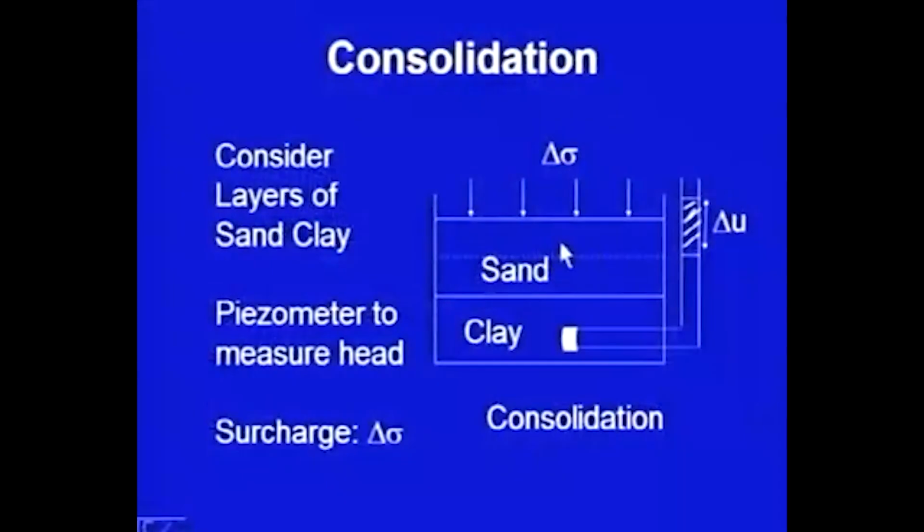Let me try to explain it technically. Here is a site, which has a sandy layer underlain by a clay layer, and let us assume we are able to put a piezometer here, and somewhere here the water table is there. Now, a surcharge is placed over here.